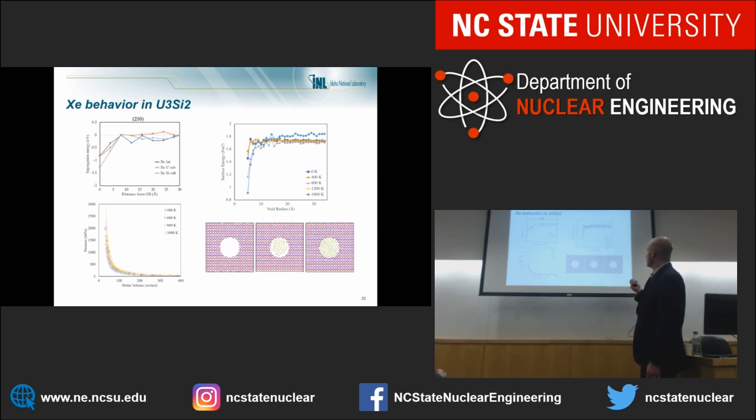We've been able to get void energies of these systems, so I'm calling this a surface energy. The average surface energy can be approximated by looking at a void, and we're showing how at very small r voids the energy of the surface is not at all what it is when it's much larger. So we're having variation in the surface energy of the void as a function of r and as a function of T.